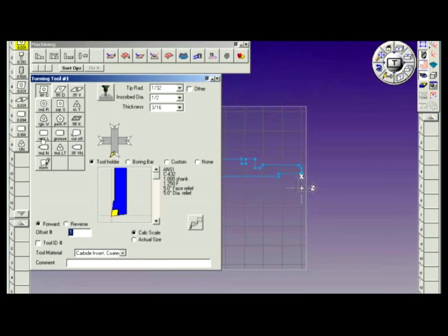We can define rectangular, grooving, cutoff inserts. Threading inserts are defined like the normal top-notch style, the lay-down cresting style, and a 35-degree with a radius. A form tool is defined by drawing geometry at the origin, the point of contact is at 0. So depending on how you draw your geometry, you control the touch-off point by placing that portion of the geometry at 0.